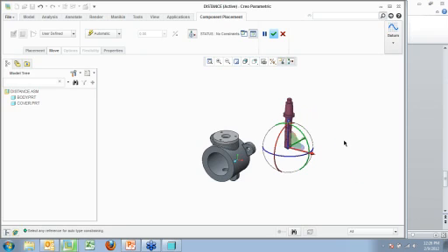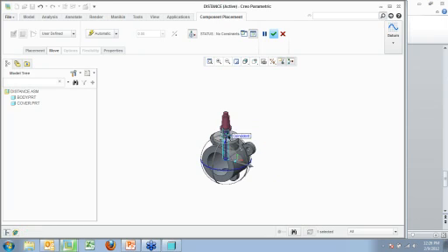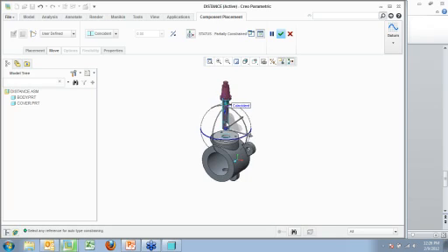So let's say I want to go in. My favorite feature about this is, notice this is purple, by the way. That's going to change in a second. I'll go in and select this cylinder and this cylinder. Now notice that most of those are grayed out. I can still grab it and drag it, but I can't drag it this way anymore. I can't drag it that way anymore. These planes, I can't drag it along those planes. I can only spin it, and I can only drag it up and down. Those are the two things that my one constraint does not constrain.